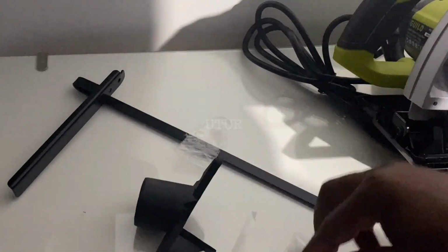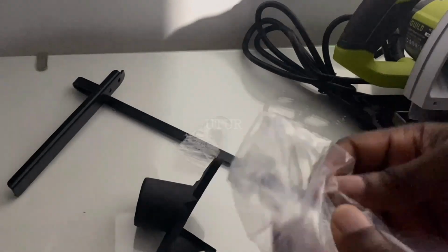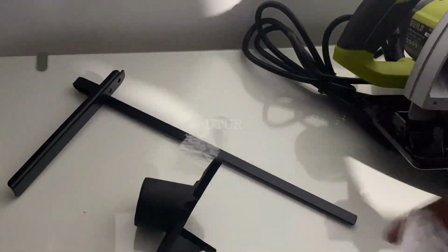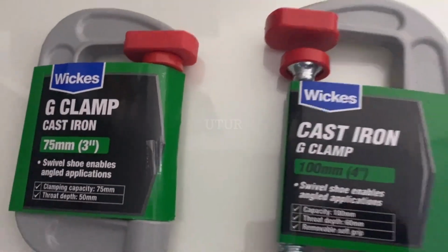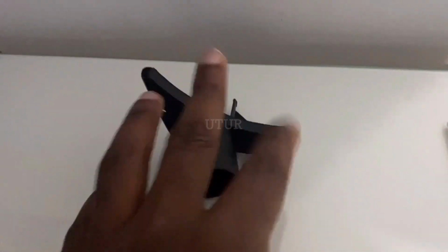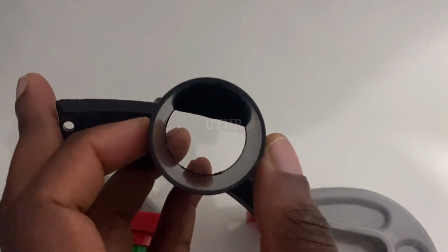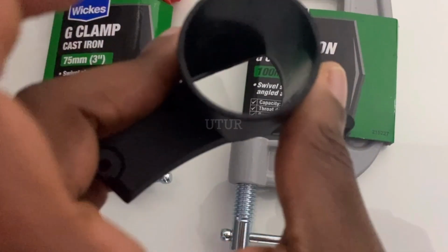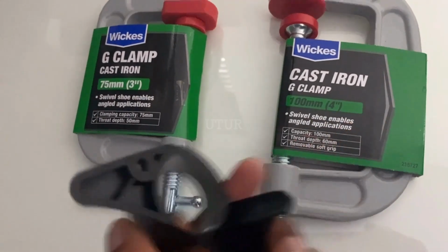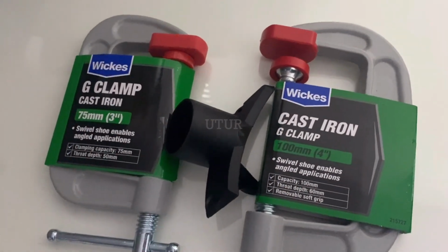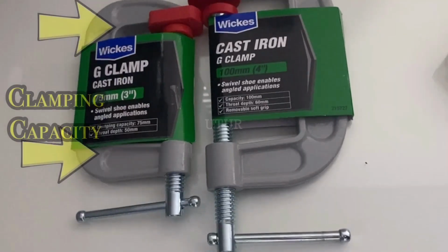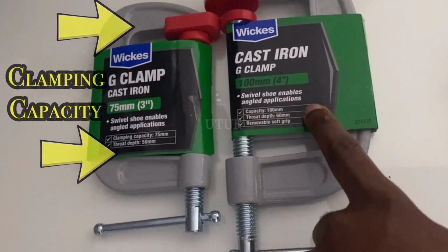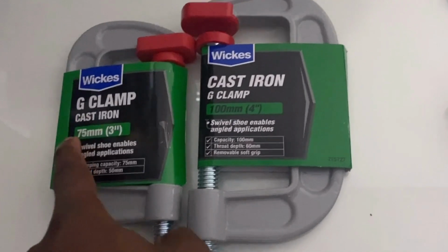Here, we've got a vacuum adapter that installs into the vacuum hose. Here, them 2 screws secure the vacuum adapter onto the circular saw's fixed guard. You can use the vacuum adapter without installing the vacuum hose. That's pretty much an option, but just take cognizance that your work area will be very messy. So you might want to modify the vacuum adapter with a wood extraction adapter, which I will be showing you in a minute.